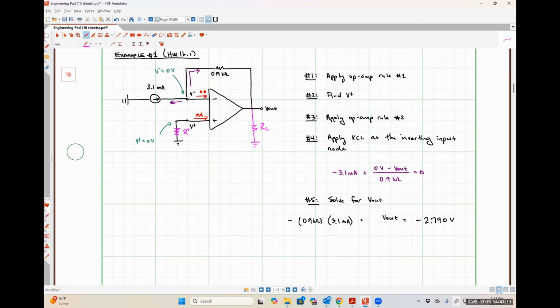No, it shouldn't. It shouldn't because there's no current flowing through that resistor. Because if current flowed through that resistor, there would be current flowing into the input terminal. So having a resistor connected directly to one of our input terminals like this will not have any impact whatsoever either. Again, from an analysis perspective, it does nothing but attempt to confuse you.